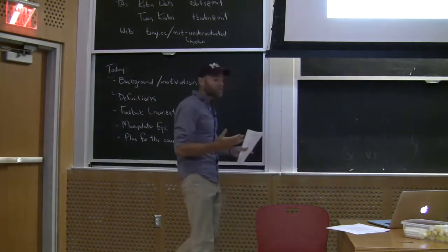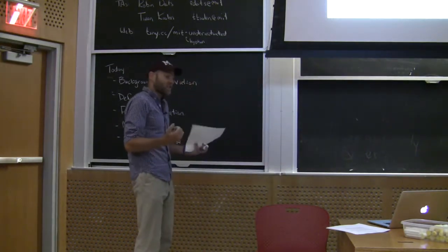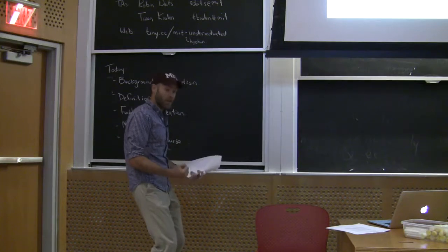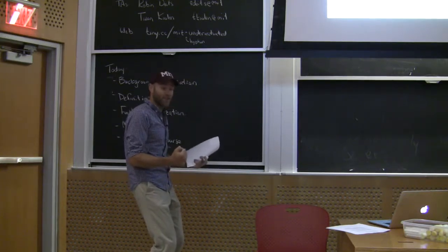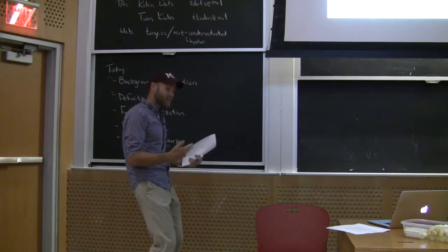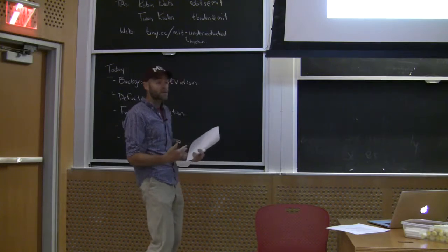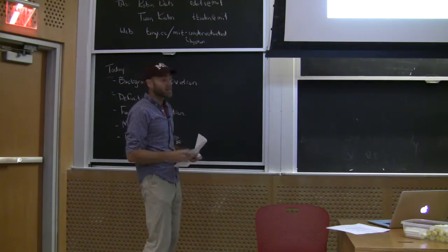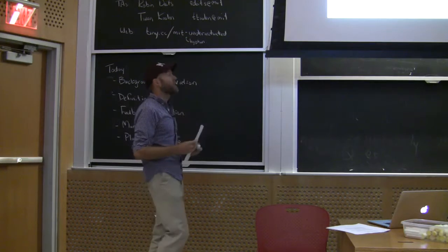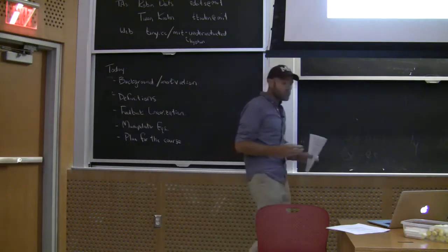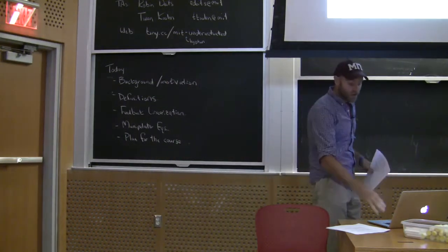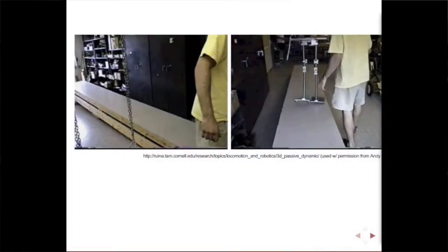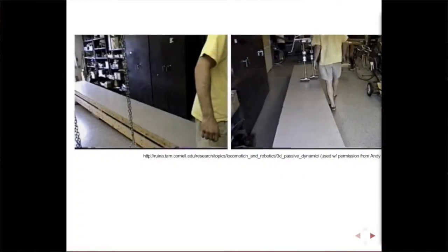It's also clear that it's not necessarily good to be walking with high gain, stiff, cancelling your dynamics. The energetics of Asimo are impressive. I mean, it takes about 20 times as much energy as a human when we walk, scaled for the mass of the robot. Okay, so there's another approach, and this is from the side. It just looks beautiful. It looks like a guy walking through the park.